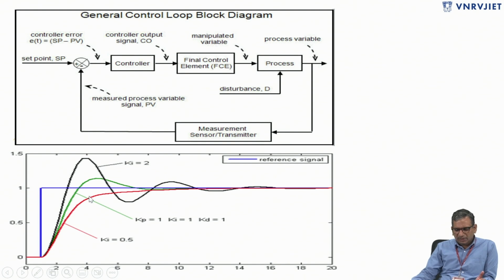If we go with the PI controller, in that case you can see that there is a large overshoot. Because of the overshoot, the settling time is also increased. But in this case we can say the steady state error is almost becoming 0. So if we have to make the dynamics or the response of the system faster, we are going to introduce derivative control.